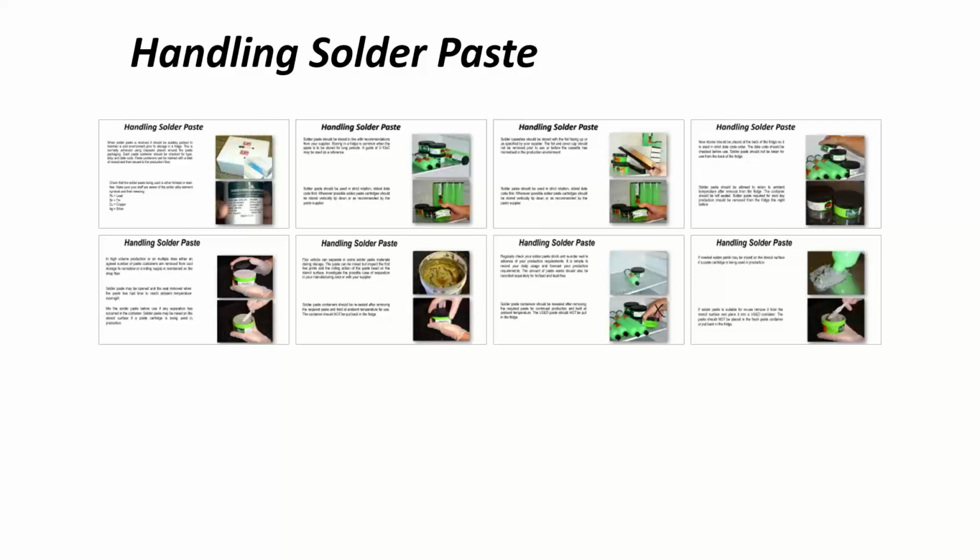When you take paste out and it's got up to room temperature, it's recovered, you've used it, if it's still printing satisfactorily, it's good practice, possibly, to reuse it on the next job. You just transfer it from stencil to the next stencil and then into the machine, provided it's still printing satisfactorily. If you're going to take it off the stencil and use it, you put it in a used container ready for reuse. You do not put it back in the fridge.